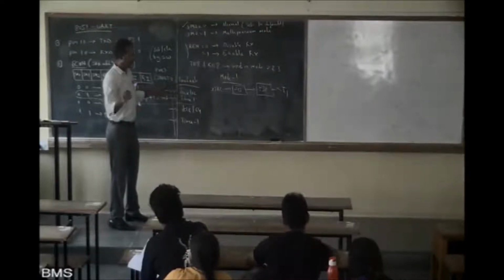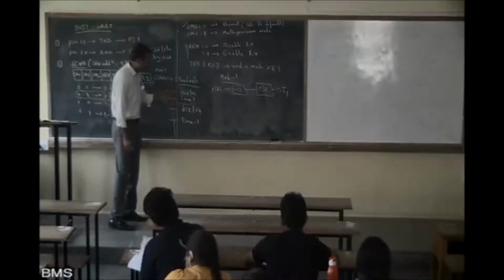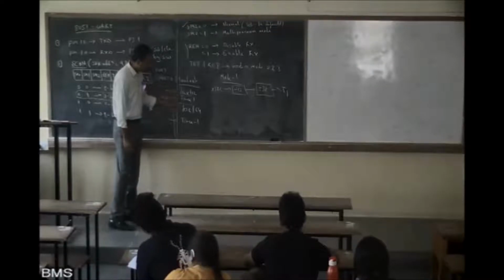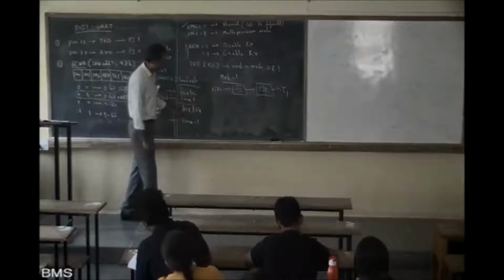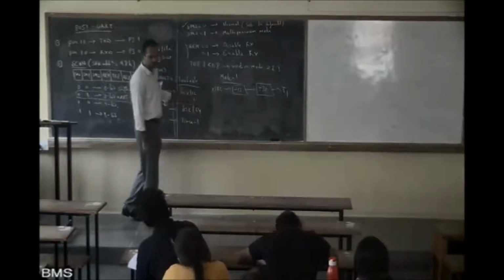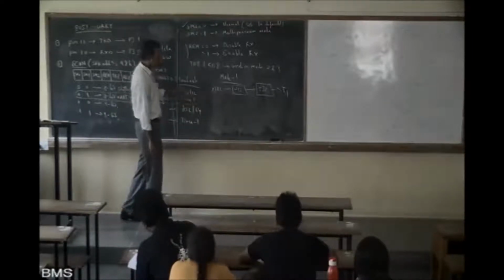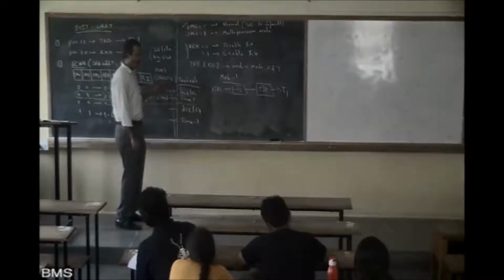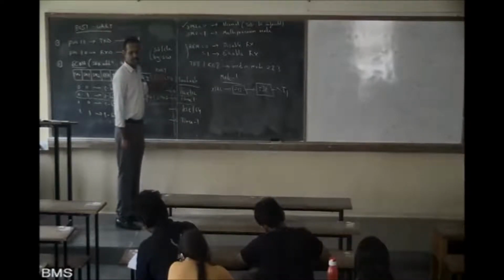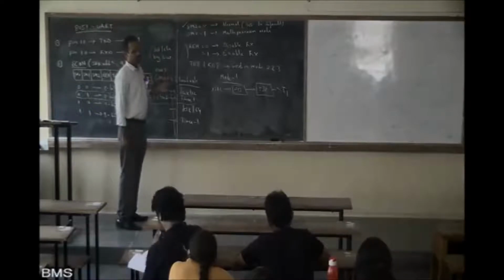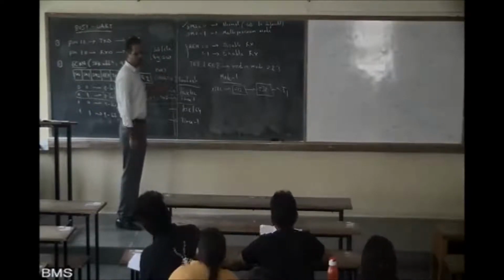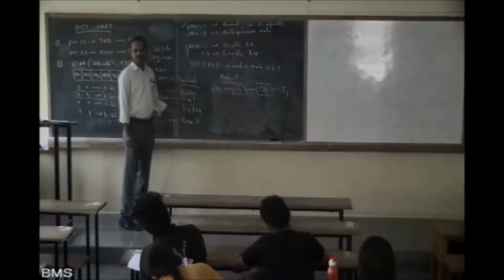Guys, you are listening to me. Please note these baud rate values. The clock frequency divided by 64 or by 32 depends on SMOD. SMOD is the 7th bit of the PCON register. If that is 0, then this is the default. So keep it 0 by default.